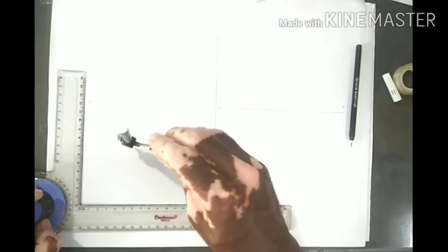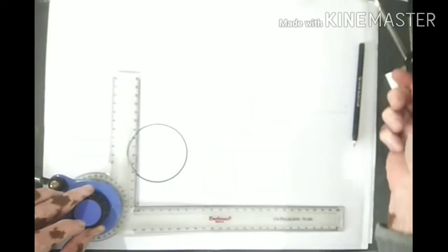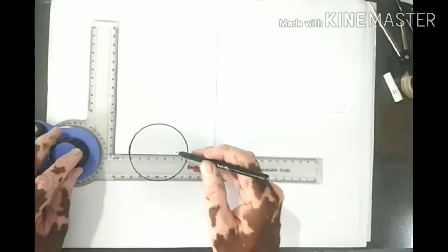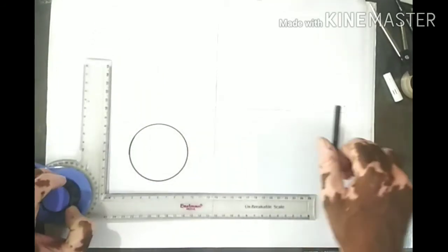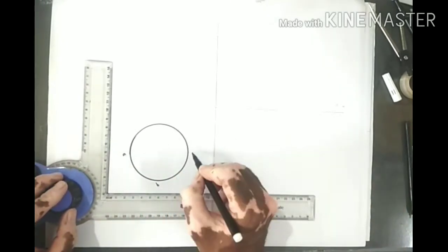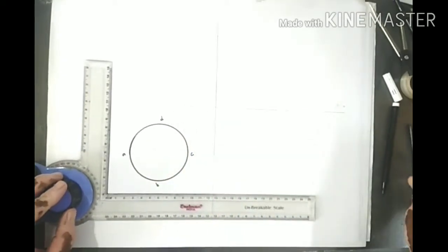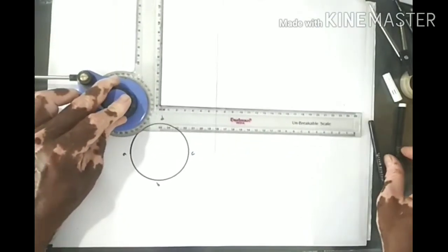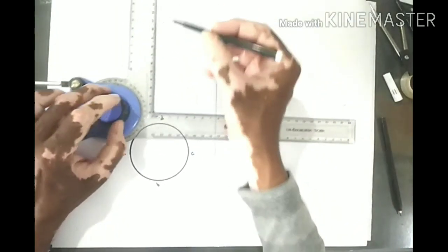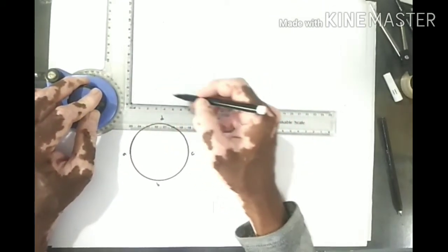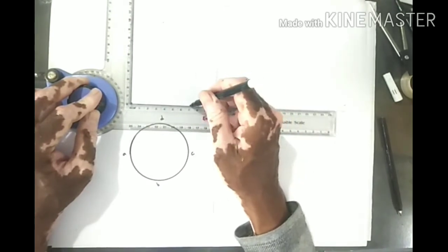And we are dividing the cylinder into 4 parts. So this A, B, C and D. Then in front view, it will look like a rectangle. Height is given to us, that is 100, and diameter is 70, means 35 mm left side of the central line and right side of the central line.